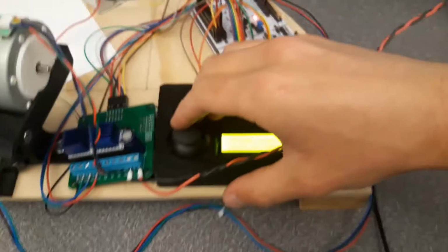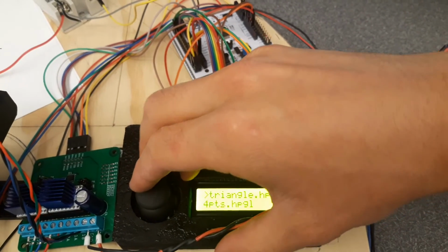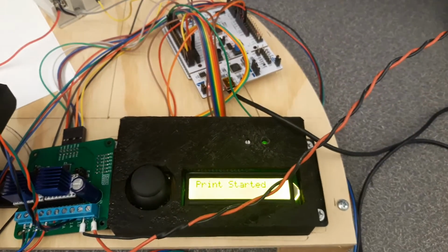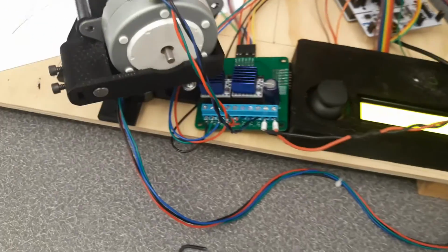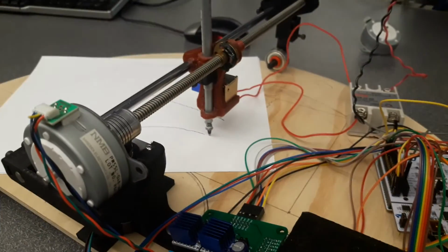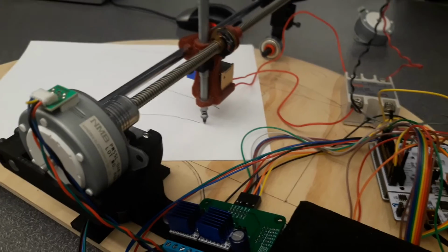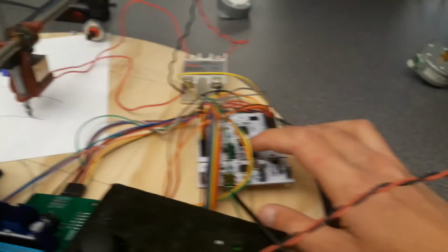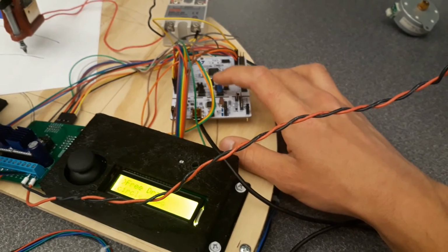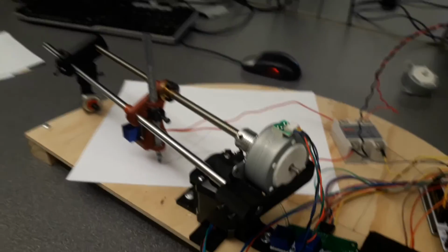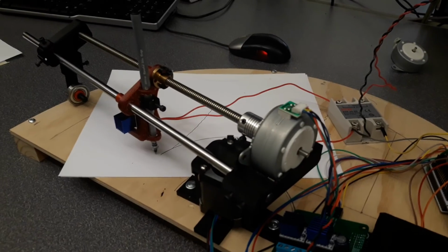So let's see here. Let's say I wanted to restart the triangle drawing. Oops. So it starts the motor. It's going to start there, and it's printing it. You can see that the solenoid is actuated, and in this case I see, oh, the radial motor is not working. I don't want to use this print because I have to swap out the radial motor. I press the blue button. It cancels it, and it moves back to where it started, so you can sort out your motor issues.